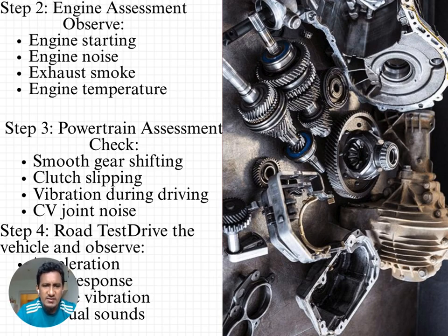At last I can say some tests we can do on the road. Drive the vehicle and observe on the road, like acceleration and gear response, engine vibration, and sounds, which is very important. When we run our vehicle we can easily do it at the time.